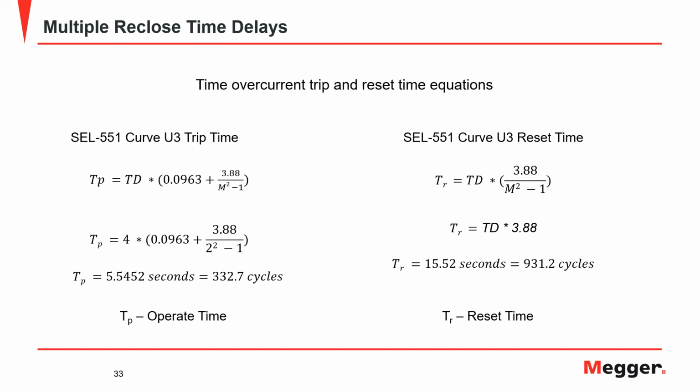So these particles are now conductive. Once you remove all that energy from them, until they dissipate, they remain conductive. So if you reclose too quickly and this particle stream still exists where the arc was, then it'll restrike through the same particle stream. You have to give these particles time to basically blow apart or just dissipate naturally, so they're no longer in close proximity to each other. But it's actually passing through the state of plasma to get there.